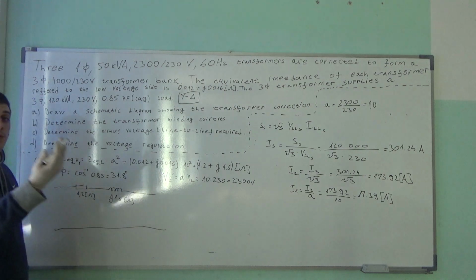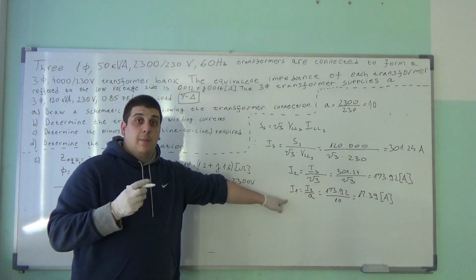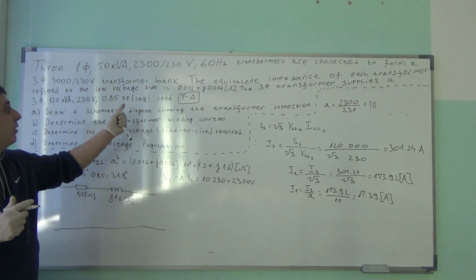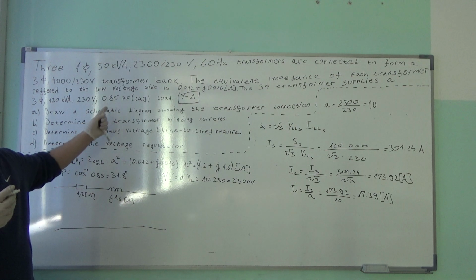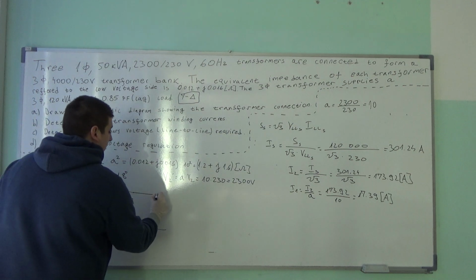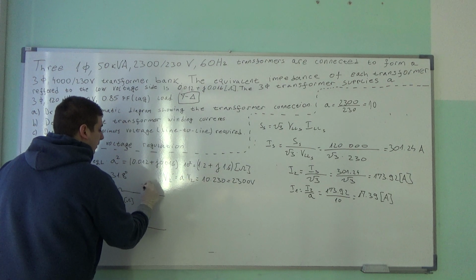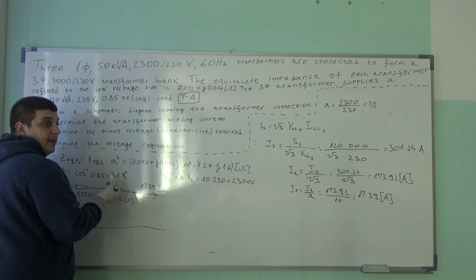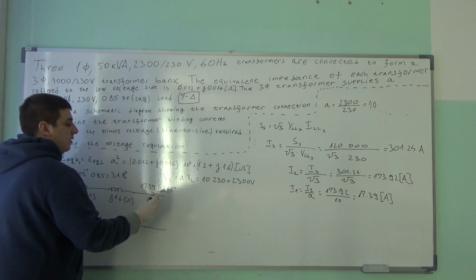Now if we refer it to the high voltage side, then we have current I1, with the lagging load of lagging power factor of 0.85, so we have the current 17.39 amperes with the phase angle of minus 31.8 degrees,